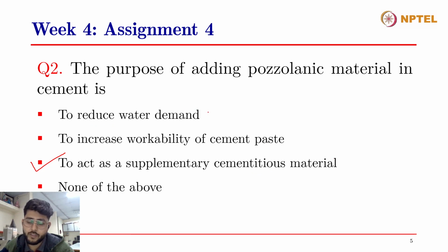They don't reduce the water demand. In fact, they sometimes increase the water demand due to their high surface area and the finer size of the particles. They also do not increase the workability of cement paste. I mean, they could provide somewhat of a plasticizing action in the case of spherical particles, but by and large they don't increase the workability of cement paste, so that is not the correct answer. The correct answer is that they act as a supplementary cementitious material, right?